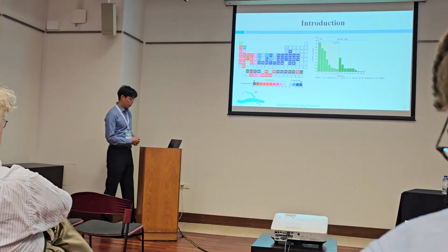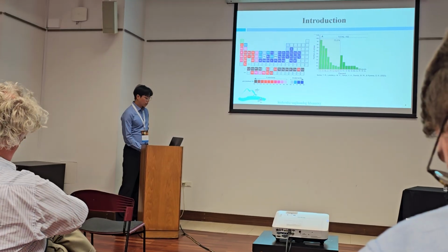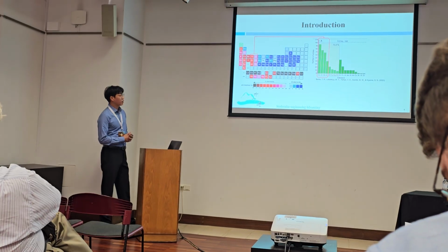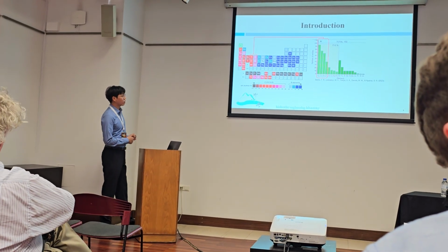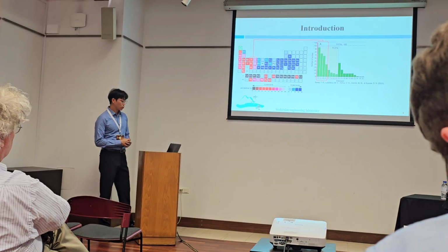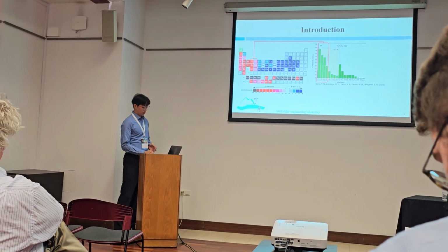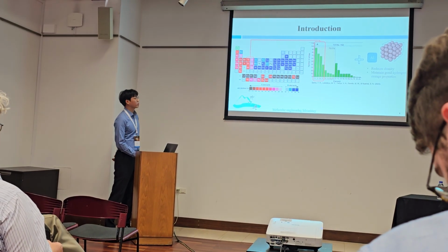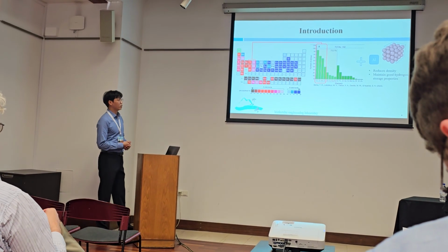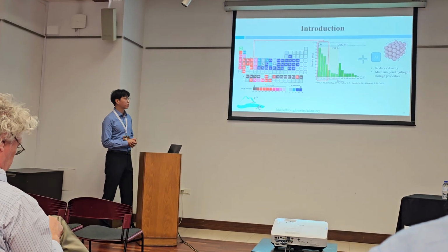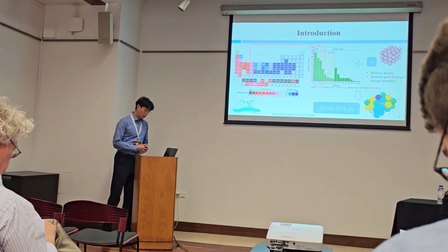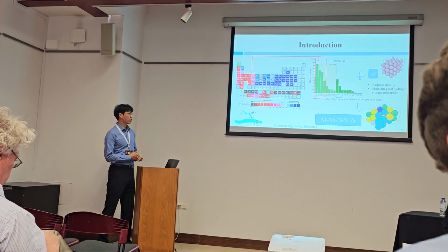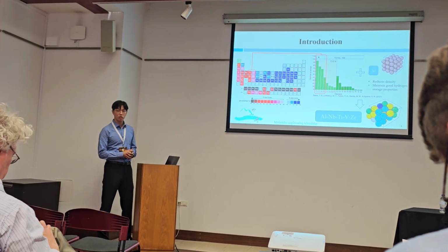Based on the frequency analysis of BCC hydrogen alloys, we know titanium, vanadium, niobium, and zirconium are the most used elements. And we add aluminum, because aluminum can reduce density and maintain good hydrogen storage properties. So this gives us the aluminum, niobium, titanium, vanadium, zirconium five-element system in our research.